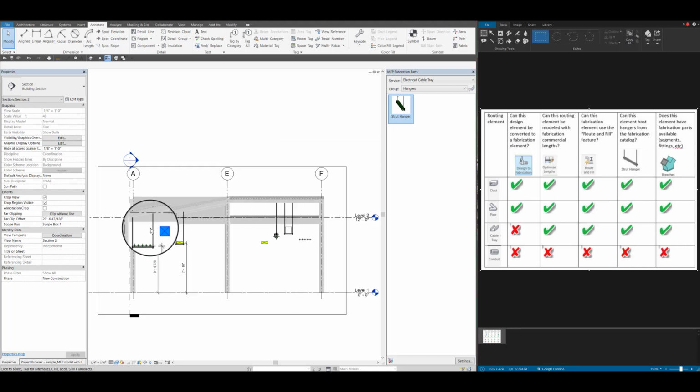If you want to plot the points to get the coordinates of the points where the hangers attach to the structure, you need to use either Trimble points or Autodesk point layout and modify the family of the hanger to include that element that is required for Autodesk point layout to find the coordinates of each intersection of the rod with the roof.